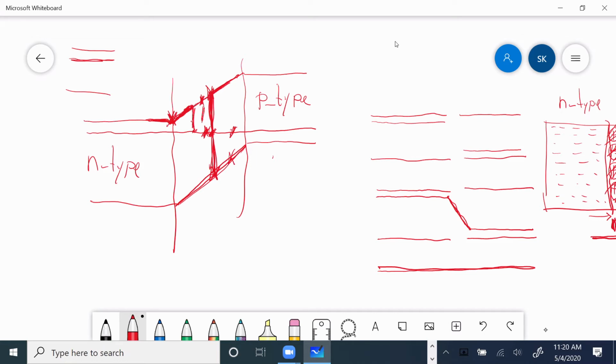So this is how the Fermi level changes from one end to another. And the material, which was N-type on this side, became less and less N-type as we go along, became kind of undoped at the junction, then more and more P-type, and then absolutely P-type there.